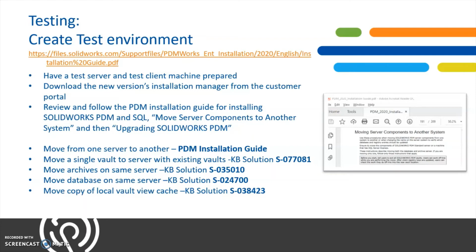Follow the Move Server Components to Another System section in the guide or one of the KB solutions shown if it applies to you. After restoring your PDM environment, follow the PDM upgrade steps in the installation guide.